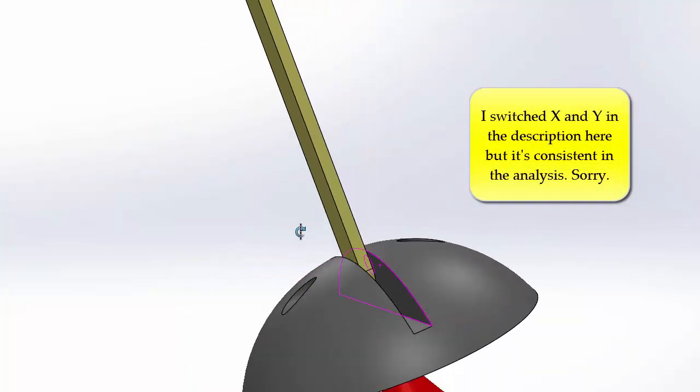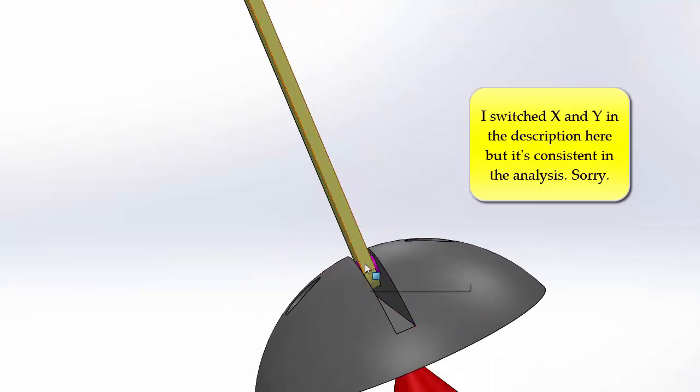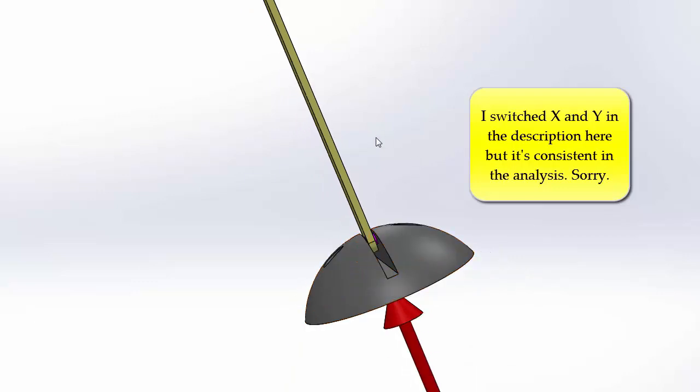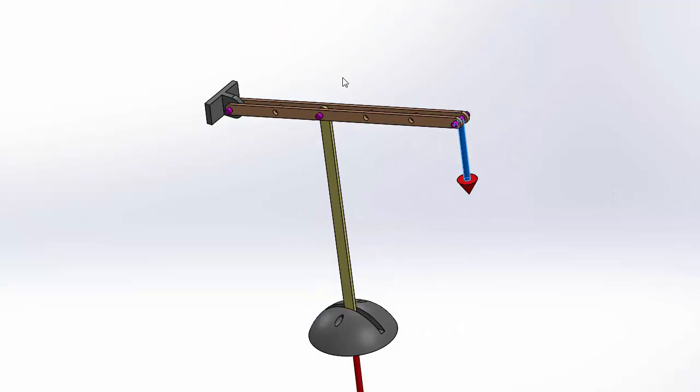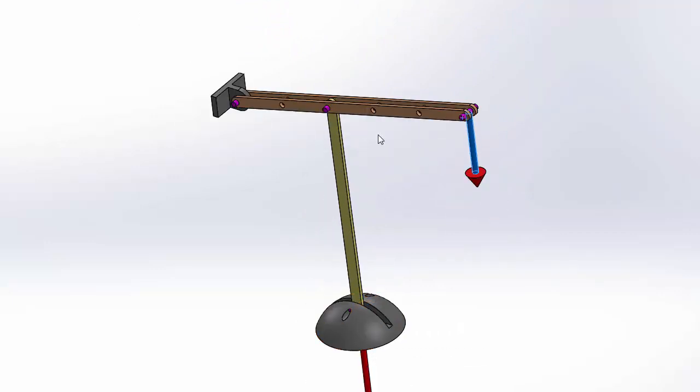But here, it's kind of held right there in place in the X. So we have 2 different ways of fixing the ends. So our end fixity factor, K, is going to be different whether we're looking at it from the X direction or from the Y direction. So that is going to affect our analysis. And that is why we have 2 modes of failure to look at.